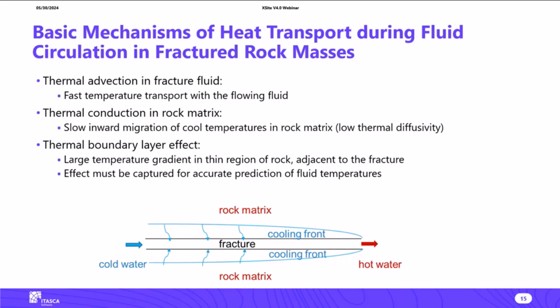So we can assume that our mechanical model is continuously in equilibrium and our flow model is continuously in a steady state, and then run the model by simulating heat advection, executing heat conduction periodically to see how much the heat front propagates into the rock, and then reestablish mechanical equilibrium and a steady state corresponding to thermally induced stress changes in the model.